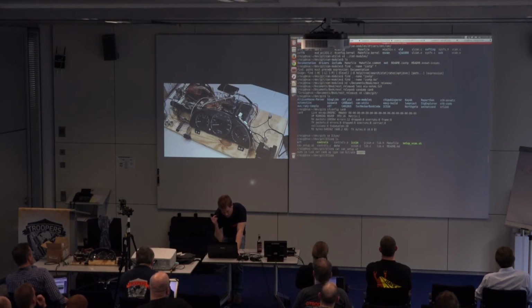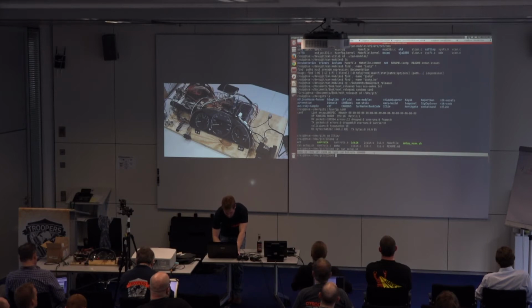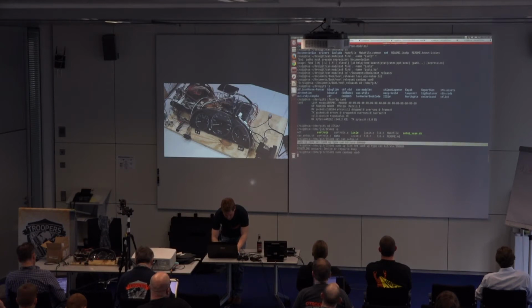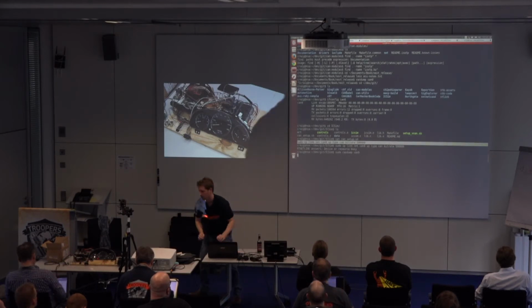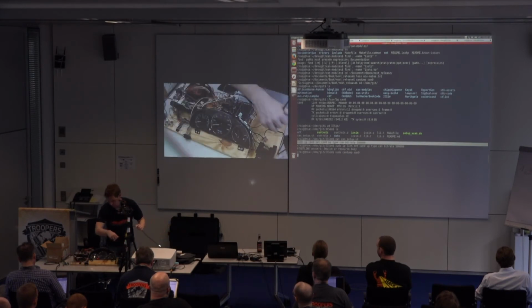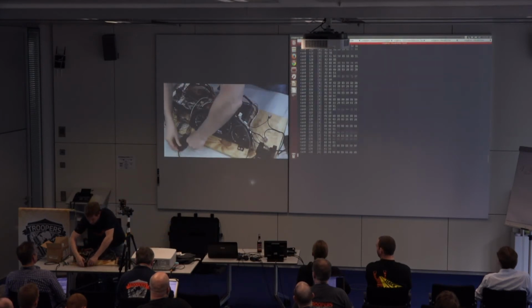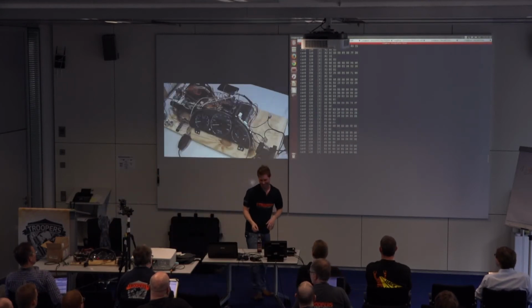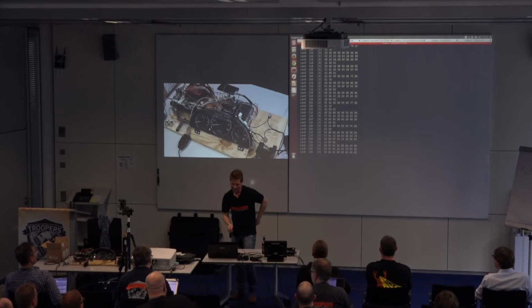This particular vehicle's CAN bus runs at 500K. So I'm just going to tell it which speed to use. Hopefully that'll solve my problem. No, it's right in there. Well, then what the heck? Oh, I'm not plugged in. That's why I'm not seeing anything. So you should plug your sniffer into the OBD port. Hey, look. Wow. Hacking. So, live demos.